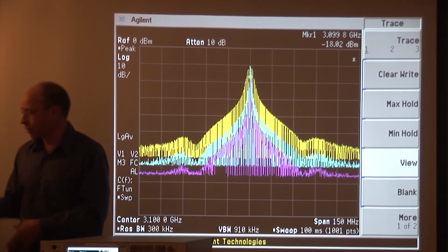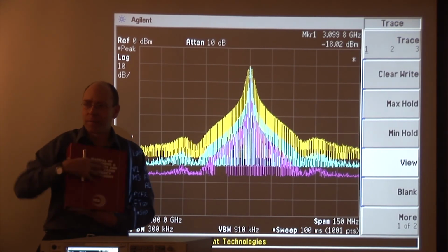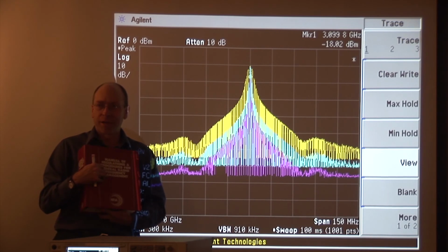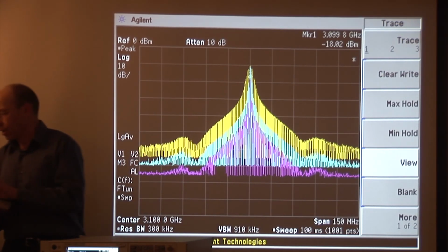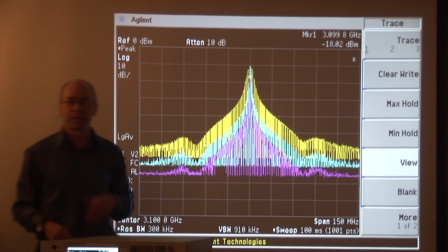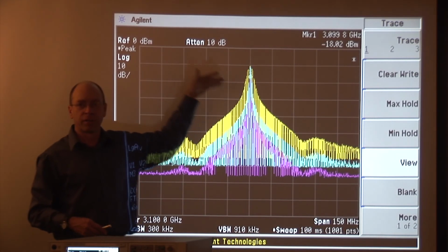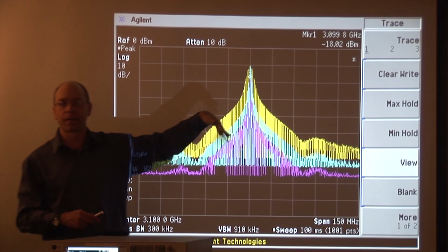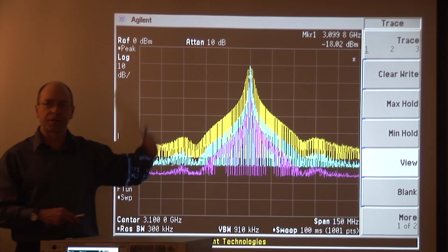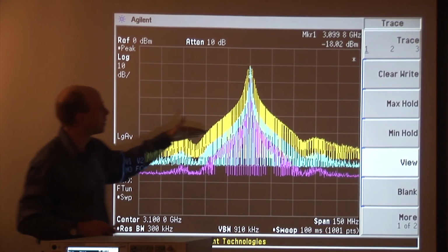But, Julie, to go back to your comment earlier, the Redbook does not say anything about a bandwidth in the measurement. The Redbook assumption is that there's a mask in the radar, either it fits it or not. The NTIA report that you can download online about how to measure radar emissions for compliance with the RSIC does address this issue, and there's a table that shows you for a given type of radar emission how to pick your bandwidth. I've been talking about simple radars that are just pulsing on and off. There are more complex radars, but the problem and the solution remain the same.